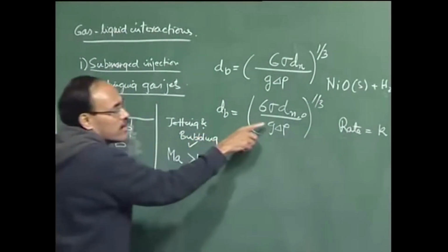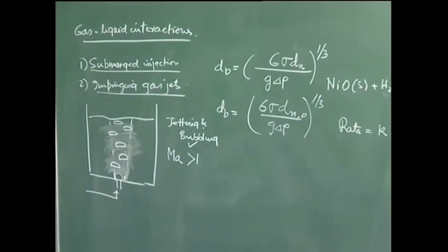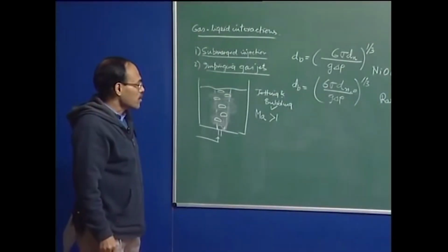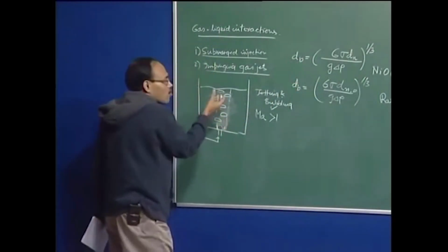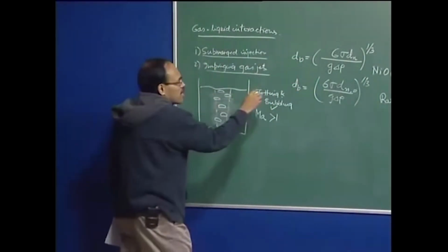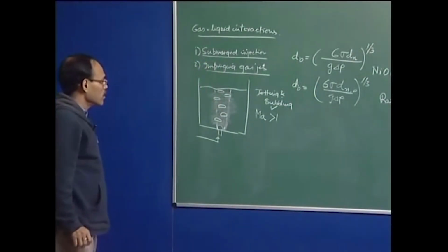On the other hand, I will take this as the outer diameter of the nozzle because of the wetting behavior of the gas in high temperature liquid metal system. So, the small bubbles forming at the orifices are going to be calculated, but these are single bubbles forming at the orifices. Very rarely are such conditions encountered in the system.